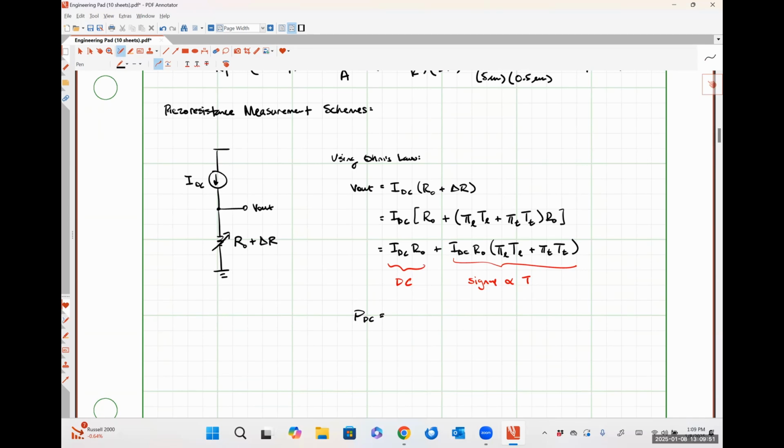And the reason why I'm bringing this up specifically is because piezo resistive sensing is great, except that it constantly consumes power, right? Because we have to constantly drive a current or something like that through a resistor in order to make our measurements. So we're always absorbing power with this particular form of sensing. For our capacitive sensing, if we had paid attention, we would have noticed that it really only absorbs DC power when the signal's changing.